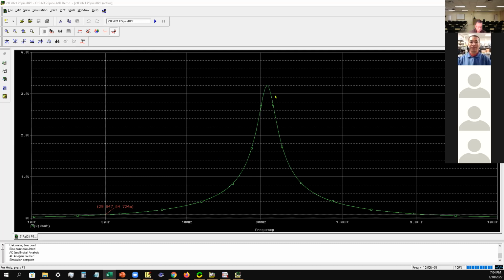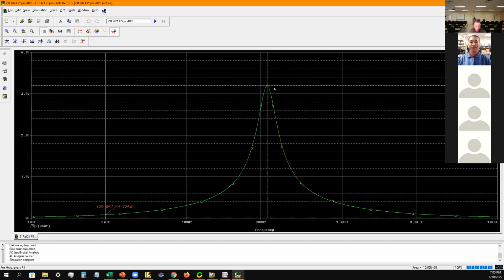Yeah, so lower you want the cutoff. You can do it in the schematic, and let me see if you can click on the one that maximizes here. So it takes me directly to where the center frequency is. Okay, there it is. The center frequency is 329.610 kilohertz at 3.1907. See, it's way beyond what we put in, which is 3 volt.